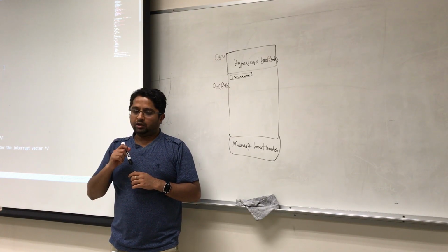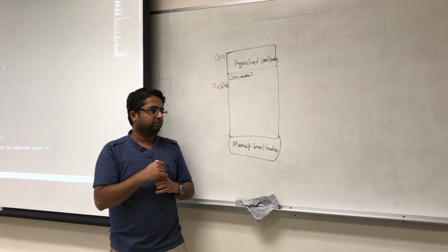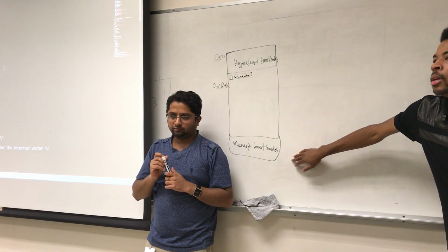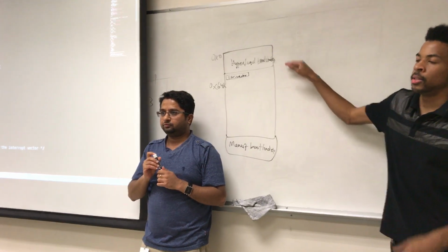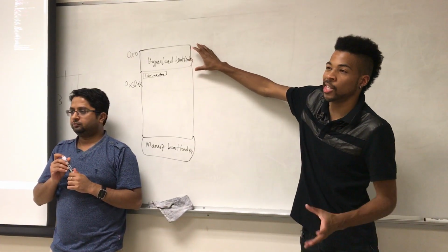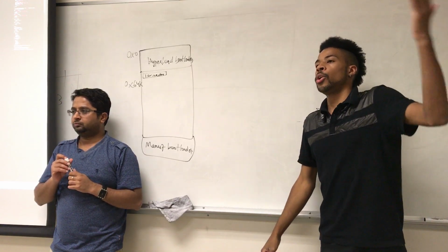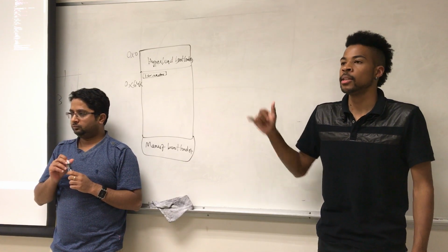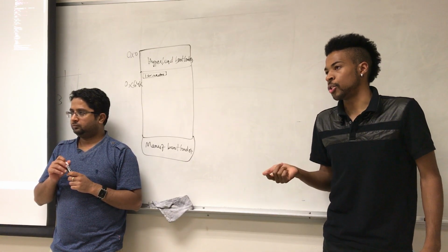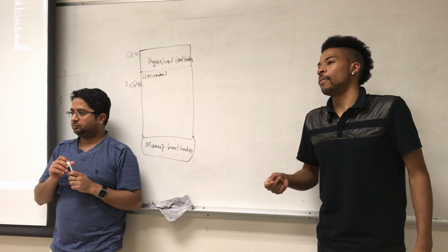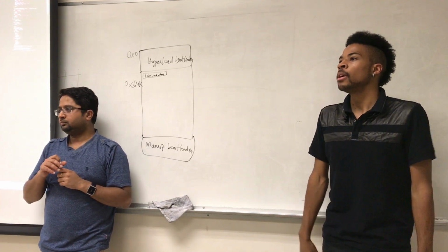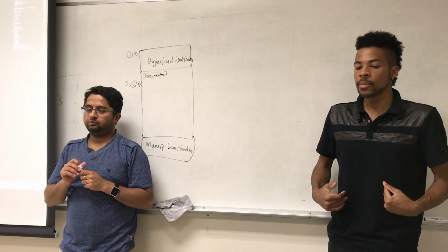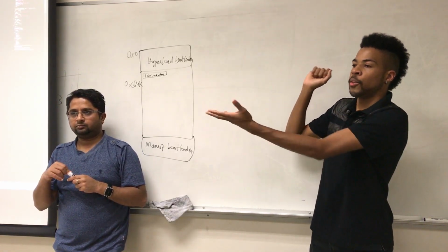No, not exactly. So the manufacturer's bootloader runs, then it'll jump to basically our user code. So hyperload's kind of considered to be a part of our user code. When we go into our user code, hyperload basically negotiates with any serial device connected. So it'll spit out the FF that you normally see on your serial. And it says, hey, if anyone sees this FF, I want to see back like I think a 5.5. If it gets back a 5.5, that's how it knows, okay, I'm supposed to be set up to start loading. And then it'll send back some other things to do some handshaking.